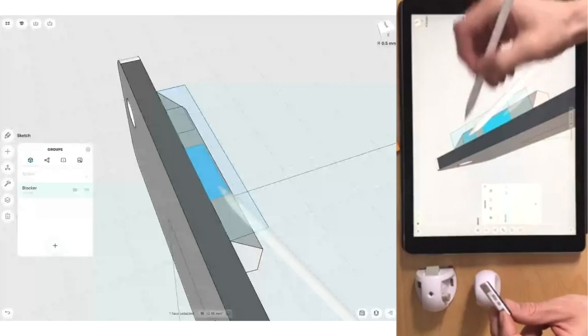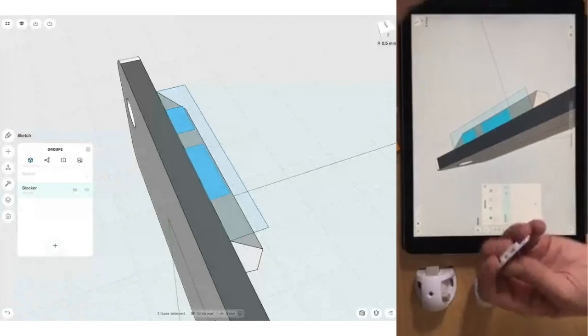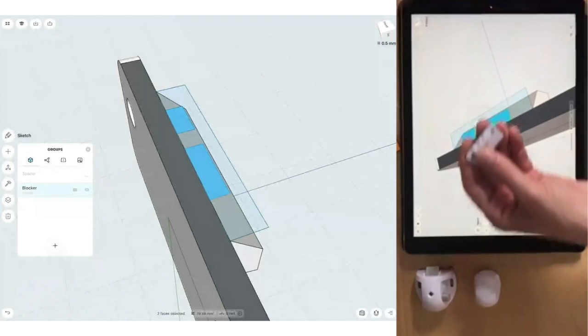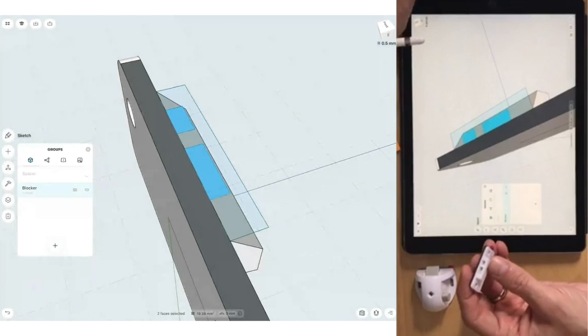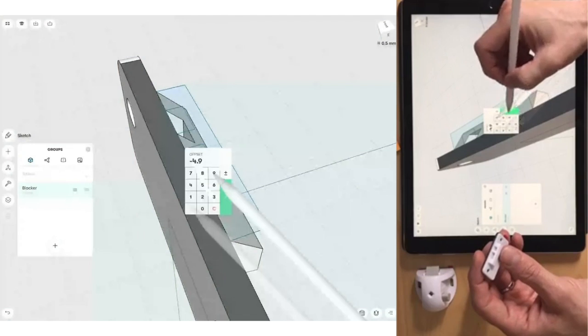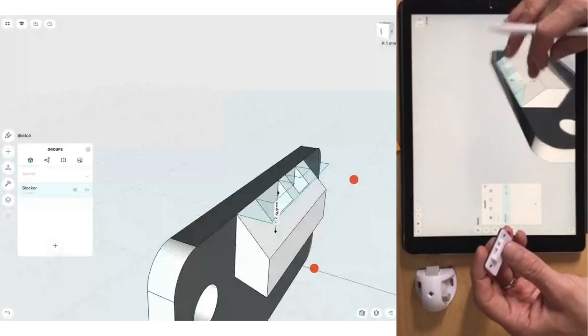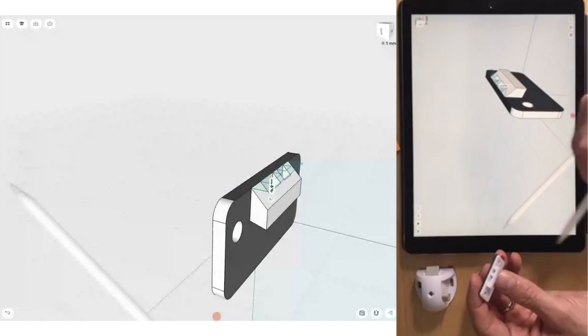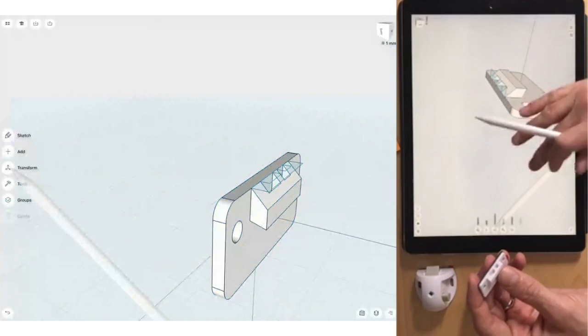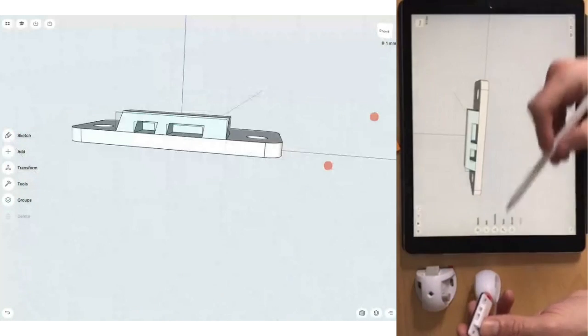and select these two. Now we need to figure out what's the distance. So if I push this one in, 4.9, so type in 4.9 and extrude into it and cut the object. Now I can go ahead and assign the color, and there we are.